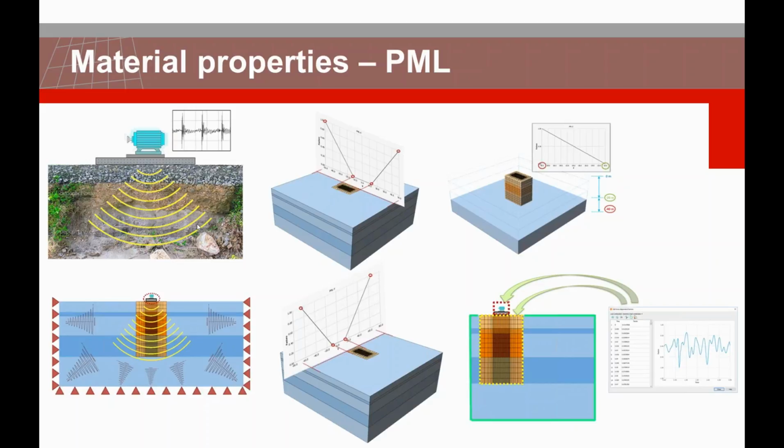The whole strategy is to reduce the size of the soil and use this specific type of element, PML layers. And through that, we absorb or dissipate the energy or the waves that are propagating in my soil medium. So this way, in terms of the analysis, we consider the soil model small. We extend that several times the dimension of the reduced soil in the model. And based on that, we can capture the elastic wave propagation which is developing in our medium.